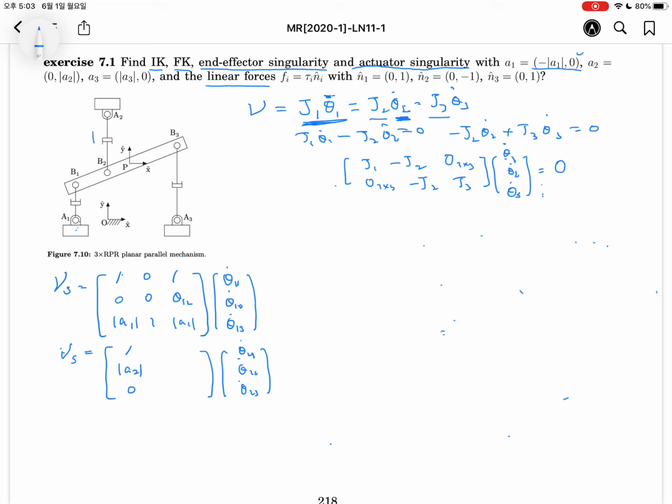Okay, how about the second, this one? Theta 22. Okay, this movement can be associated with the screw axis of the second joint. So there is no rotation movement. It is corresponding to the minus y. So 0 and minus 1. Because the linear movement should be normalized as a unit vector if there is no rotation movement. That is the definition of a screw axis.